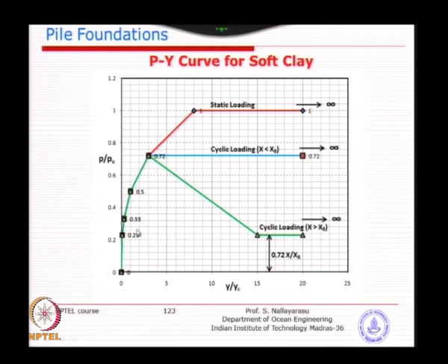The one that we were looking at earlier on the first table is the green line followed by the red one. So, basically the maximum capacity occurs at 8 times Yc, you can see here this is 5, 6, 7, 8, at 8 times Yc you get a maximum ultimate capacity of Pu, and after that it becomes plastic deformation.